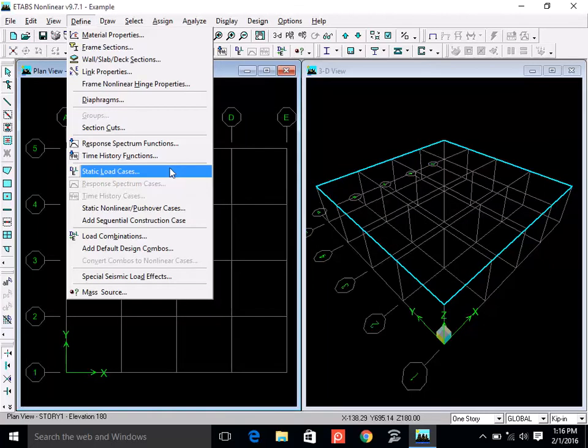So you can go to load cases and say, okay, only run analysis for earthquake, and the remaining you switch off. So that will save you time. But in the older version, you don't have that facility. Then the next one, after load cases, we shall use load combinations.